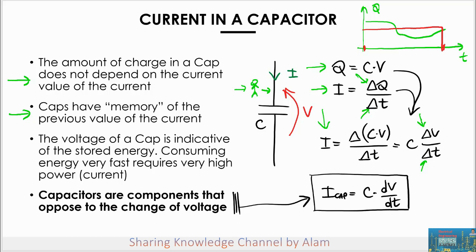If instead of that time period, you chose something where the delta T is, let's say, one third of the initial delta T, so this is the delta T that you pick in that equation, well, then in that case, you will give me 3 numbers, because for each delta T you have a different amount of charge. So you have 3 numbers for the current. So you're representing the current during that period with 3 points instead of 1.